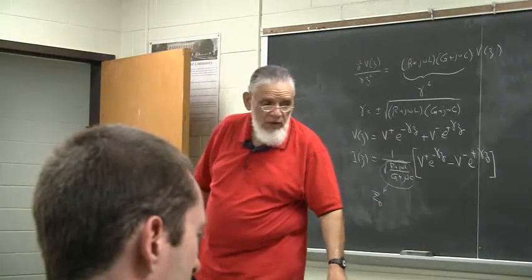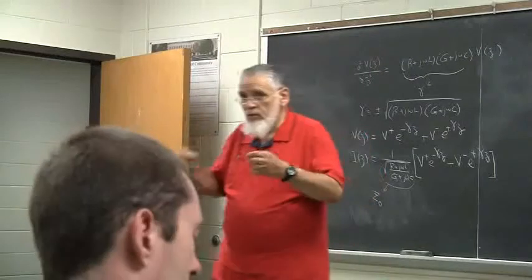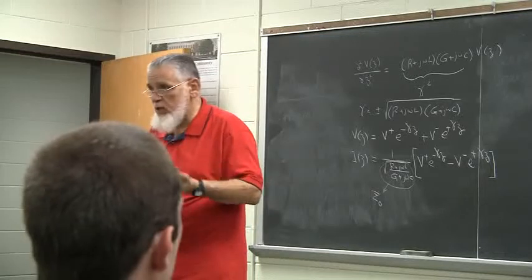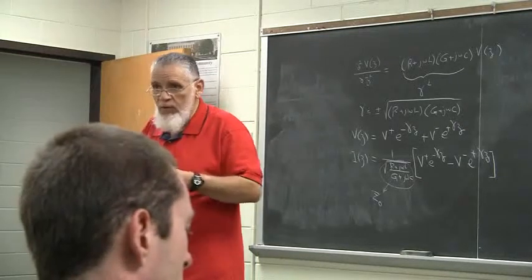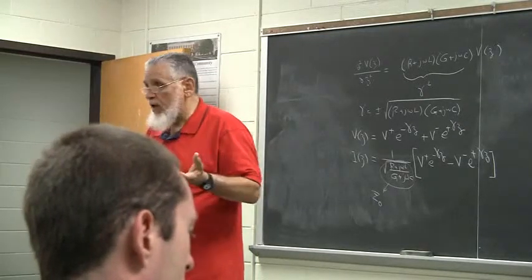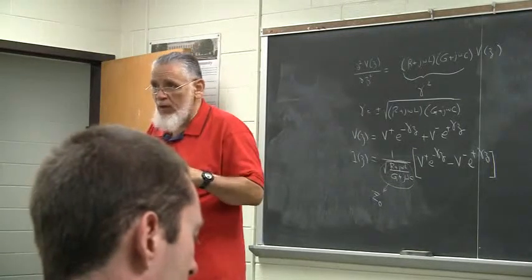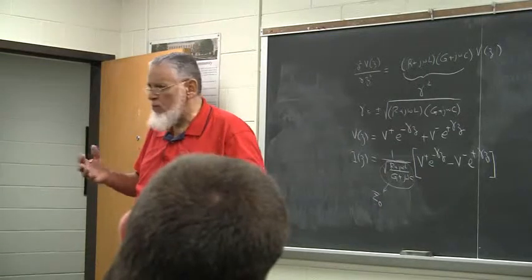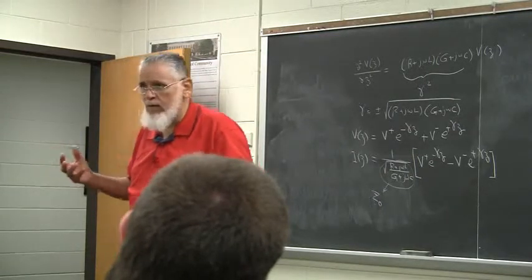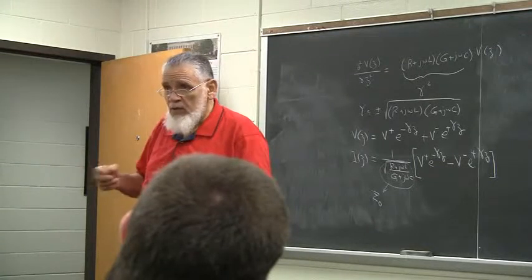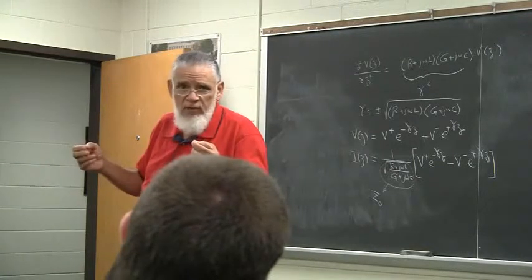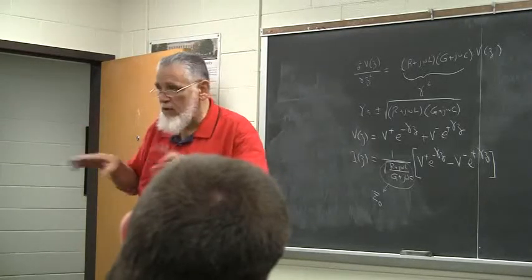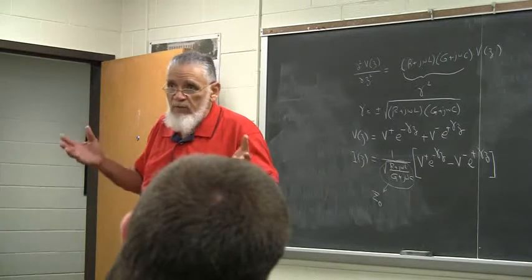So we take the transmission line, right, two conductors, develop a physical model, which is an approximation, because after all, when you take a field problem and reduce it to a circuit problem, you are doing an approximation. You are doing some sort of a modeling, and there's no perfect model. There's always some form of an approximation. So we say we can see a resistance in the center conductor, we can see a resistance in the outer conductor, or if it's parallel wires, whatever the conductors' shapes are, there's some internal resistance.